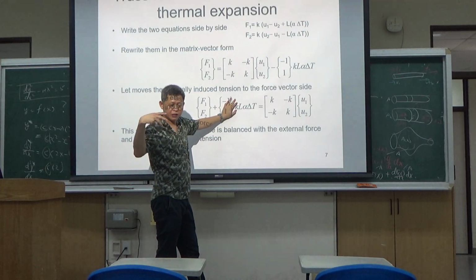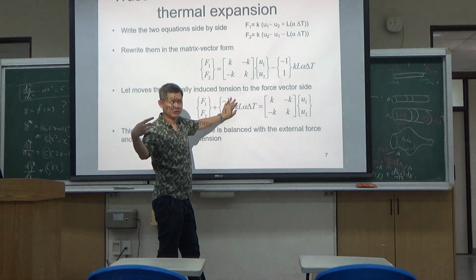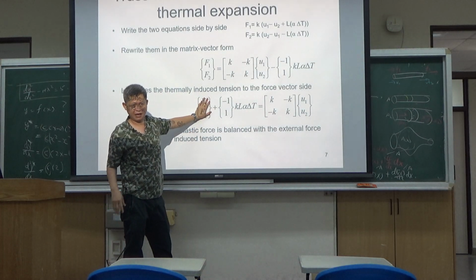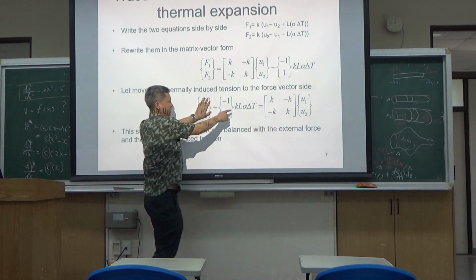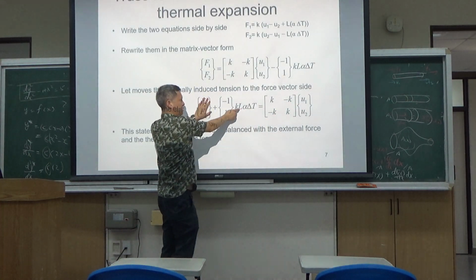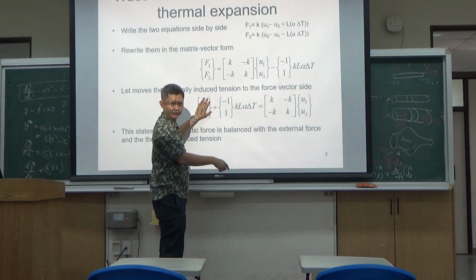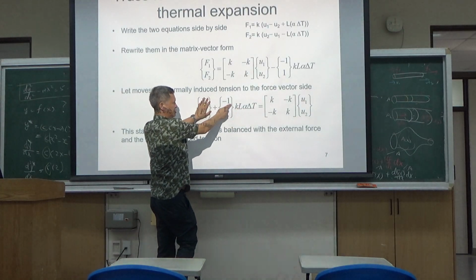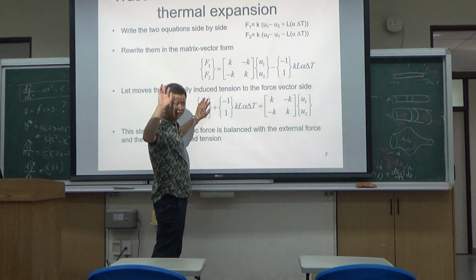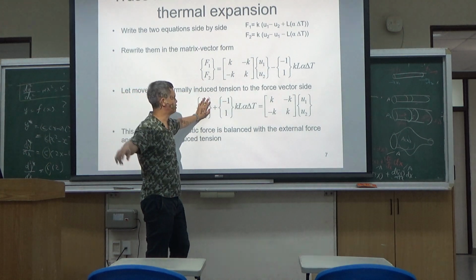But because of the thermal expansions, you see that even if you have zero force externally, heating will cause the right hand side to elongate. Elongate by how much? The elongation must be equal to the one caused by the right thermally induced pulling force.